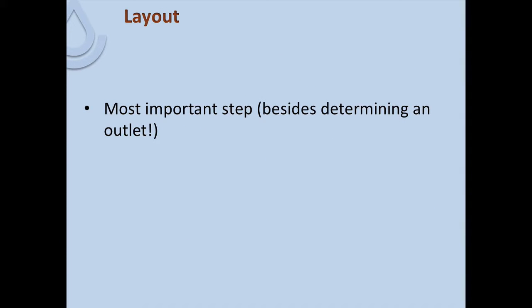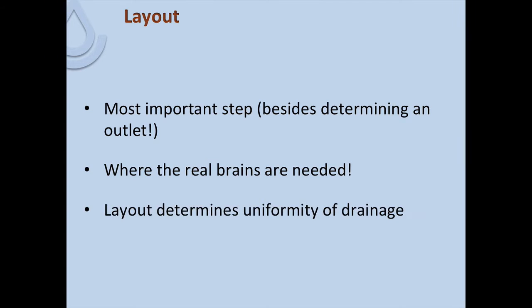Layout is going to be one of the most important steps, assuming again that we've got an adequate outlet. And layout is generally a mixture of art and science, and so it's often where the real brains are needed. And that layout is going to determine how uniform that drainage is. Layout is working with the topography of the field to try and get as consistent a depth throughout the field